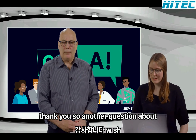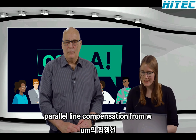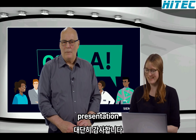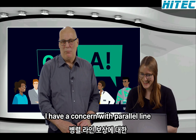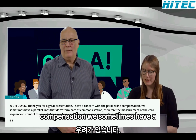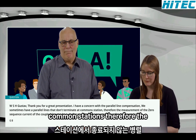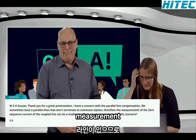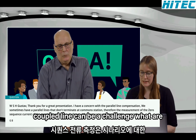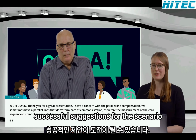Thank you. So another question about parallel line compensation from WSH. Gustav, thank you very much for the great presentation. I have a concern with parallel line compensation. We sometimes have a parallel line that doesn't terminate at common stations. Therefore, the measurement of the zero sequence current of the coupled line can be a challenge. What are suggestions for this scenario?